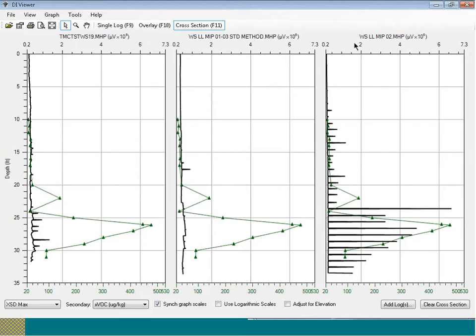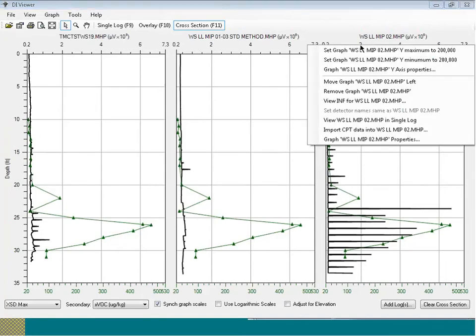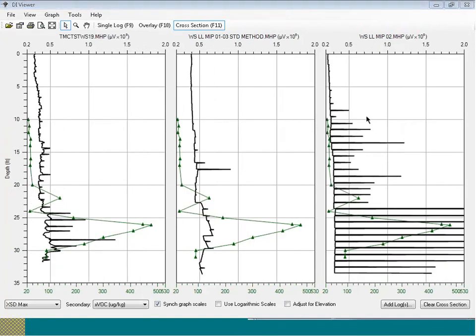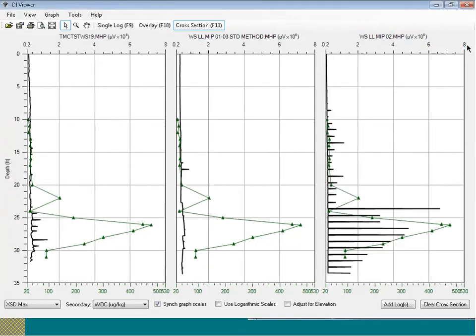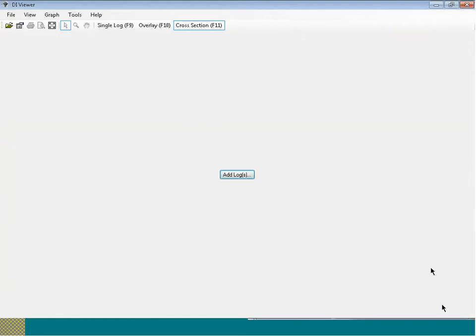Another thing I want to just quickly show, I'm going to right-click on the number 2 and set that as my maximum, and highlight down here. These responses that we got in the lab data are around 30 parts per billion of chlorinated VOCs in the soil. And it's very evident with the low-level system that we actually have impacts at that point. Obviously, where we're having it, upwards of 500 parts per billion, that's extremely evident on the low-level system.